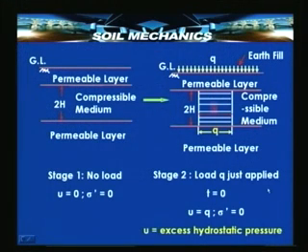Now, in the second stage, where q has just been applied, we start counting the time for the compression phenomenon. t is equal to 0, and the entire load is carried by water, and therefore, the excess hydrostatic pressure u in water is equal to the load applied, that is q, and the corresponding effective stress is 0, and the excess hydrostatic pressure is now at its full or maximum value, that is equal to q.